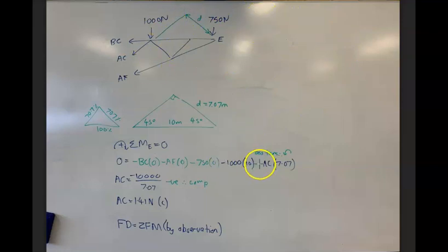So we're right, negative and negative. Now we've assumed tension. The only reason it's going anti-clockwise is because we assumed that it was pulling out. In this case, what we're going to get as our answer is 10,000 divided by 7.07. We're going to get a negative number, so therefore our assumption was not correct. It means we're in compression. AC is 1.41 kilonewtons, which is in compression.